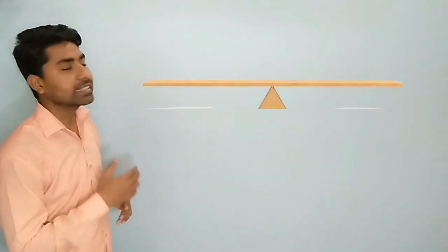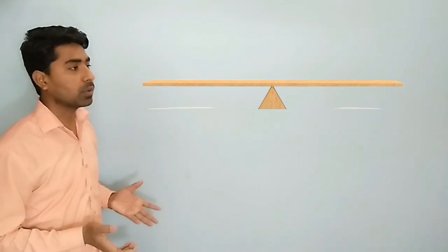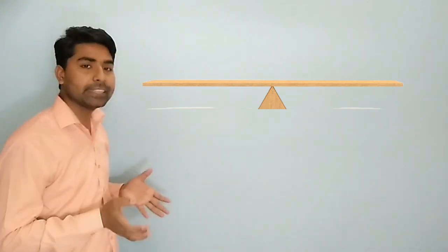And the seesaw, this one. In this case, the effort arm and load arm both are equal. So this is used only to change the direction. So remember, class 1 lever can perform all the 3 types of functions: as a force multiplier, as a speed multiplier, as a change of direction. It can perform all the types of functions.